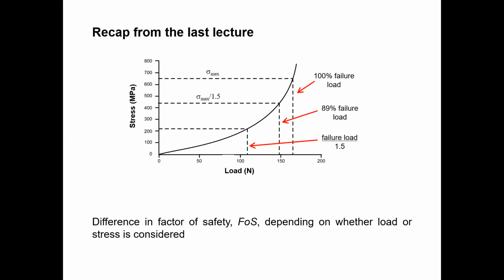You are going to apply some value as a load. So don't use the stress value if there is a nonlinearity like this. If you identify there is a kind of nonlinearity, don't use stress to calculate the factor of safety. That is the meaning of this point.